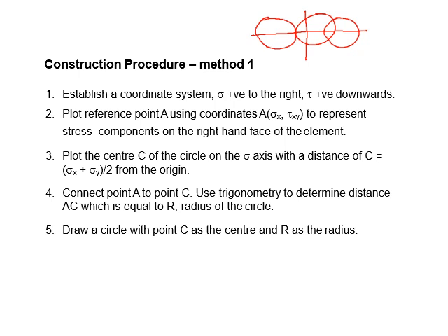So knowing approximately where your Mohr circle is will help you to determine where you want to place your shear stress axis. Is it in the middle of the graph paper? Is it to the right of the graph paper? Or is it to the left of the graph paper if your circle is on the right? Okay. And the other thing is your scale for the axis. This is normal stress, this is shear stress.